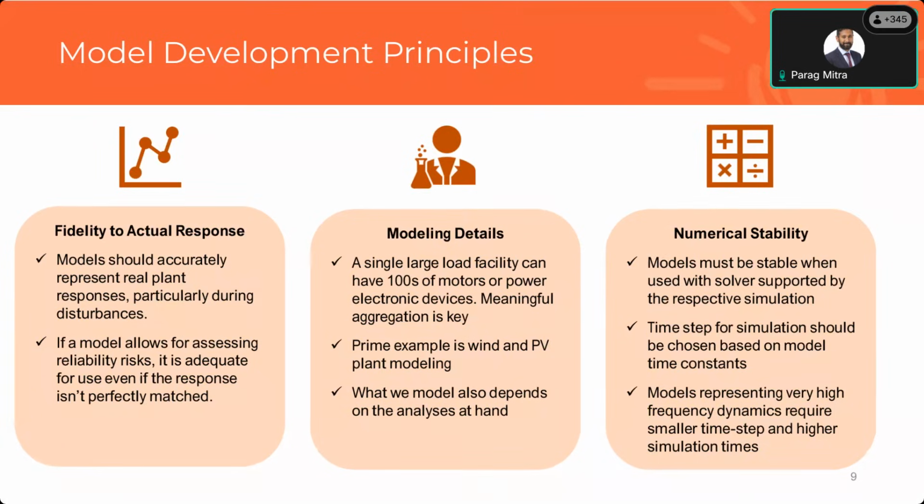Last piece is around numerical stability. When we are developing these models, we need to make sure that the models are numerically stable so that we don't confuse a solver-driven instability issue with a practical system instability issue. So we need to be very careful about the time steps that we're using.